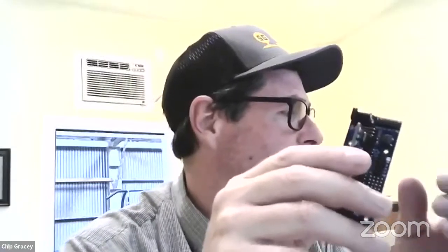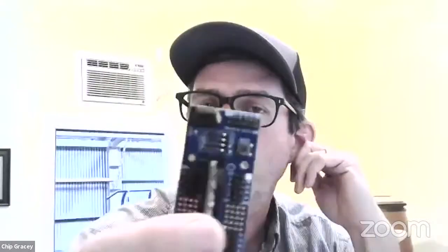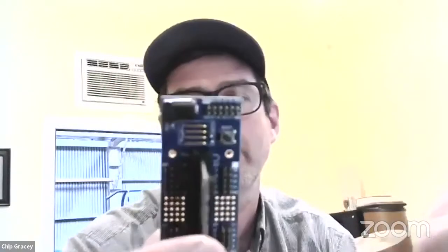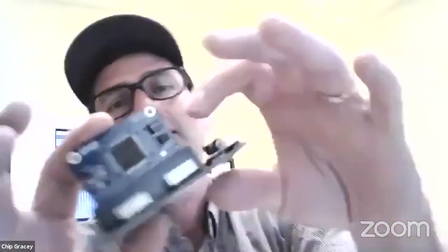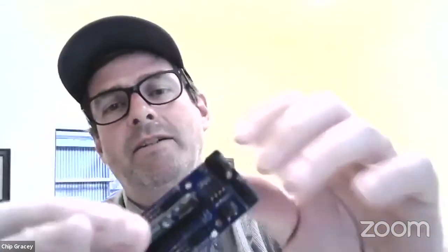But we have to do it on that one because they're going to plug in all kinds of things. Yeah, this has no components on it that are active or passive. It only has headers, push buttons, and connectors. That's all it's got. So adding regulation there just makes the thing bigger, doubles the cost.